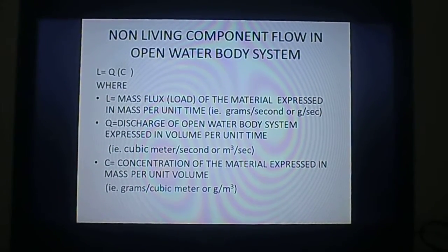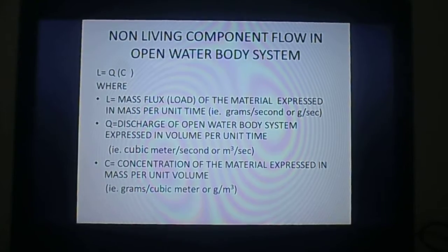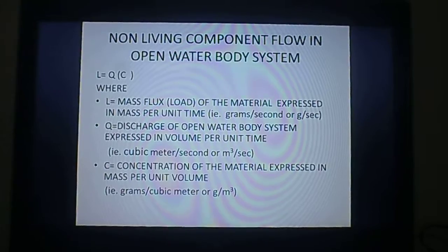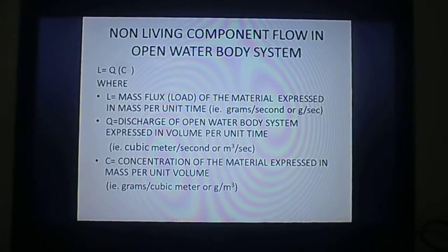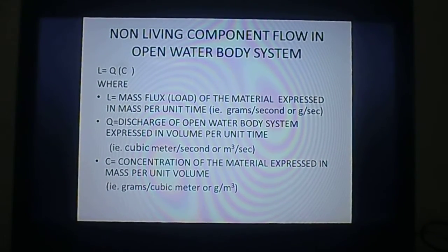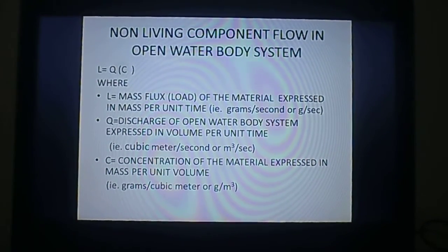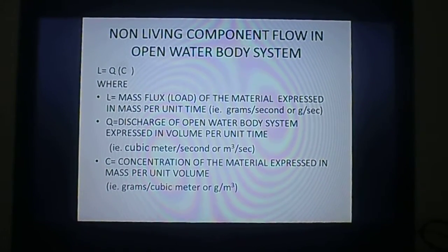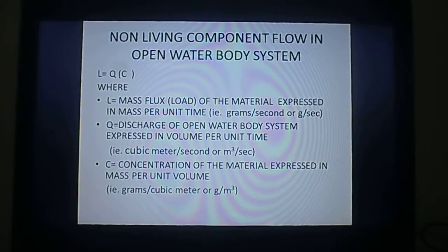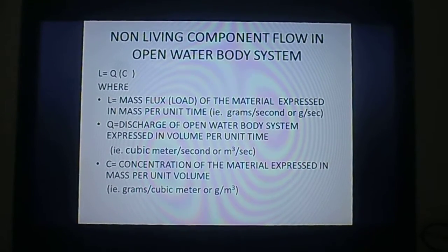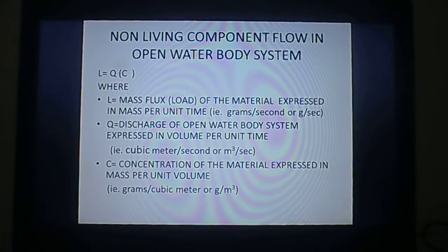In the open system water body, the flow may be expressed as L equals Q times C, where L is mass flow of the material expressed in mass per unit time, and therefore can be in the units of grams per second, where grams is the unit of mass and second the unit of time.